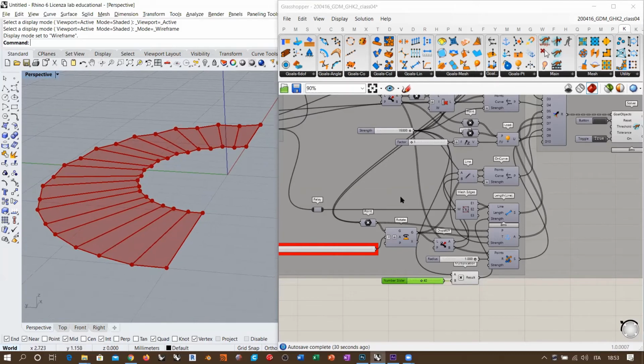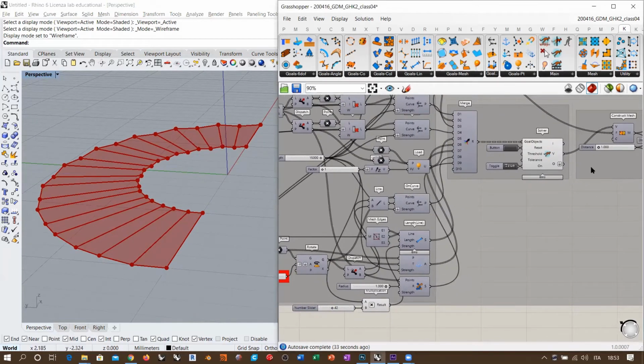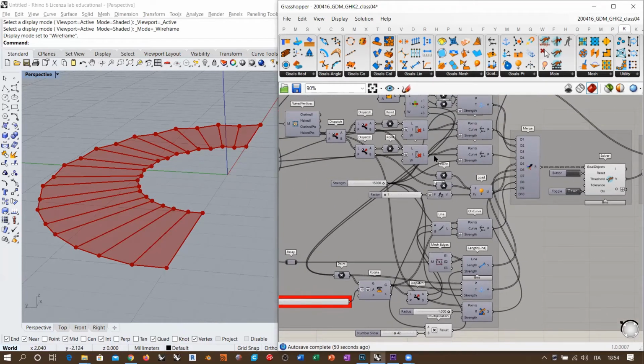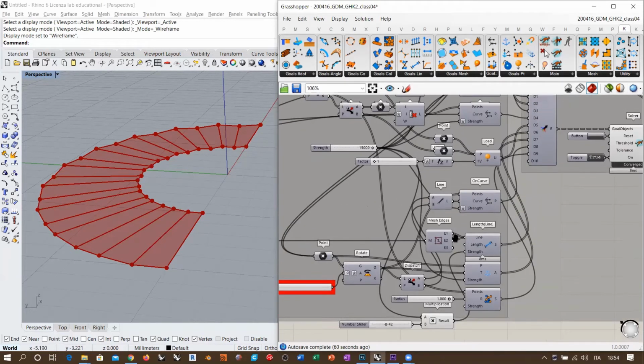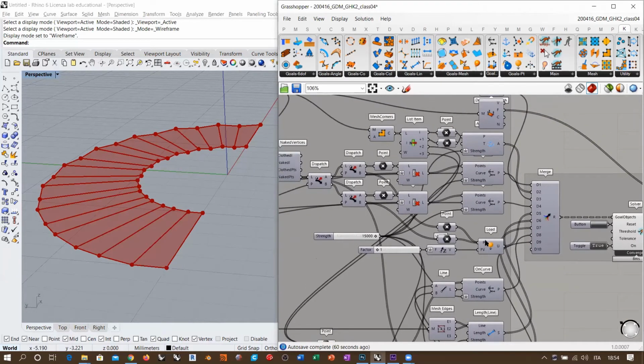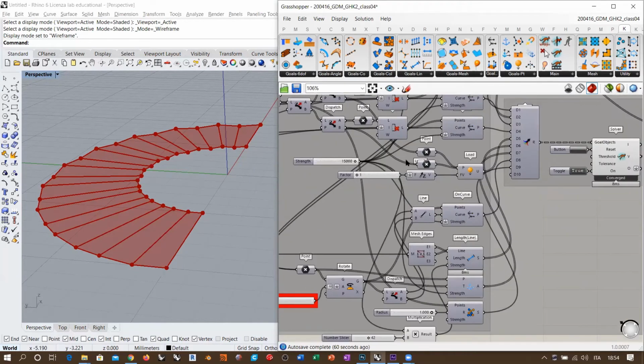It's, let's say, a light deformation. If you want, you can also calculate it before and after the simulation and see if there is some stretching of these lines, as it's evident that there is a little stretching, and see if this little stretching that is occurring is something that you might accept or not. If you don't accept this kind of deformation, you have to tweak the values of the strength of your forces. So you see that it is not enough to give more strength to the elastic bars, to the rigid bars, sorry, you should also try to tweak the values, for example, of the load and of other forces that are affecting the simulation.